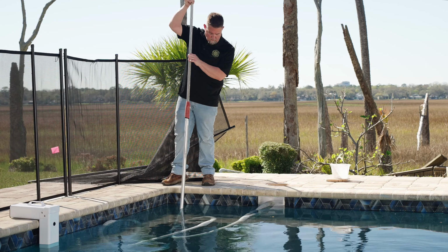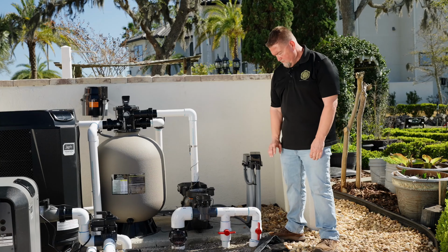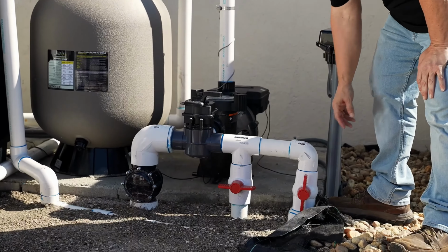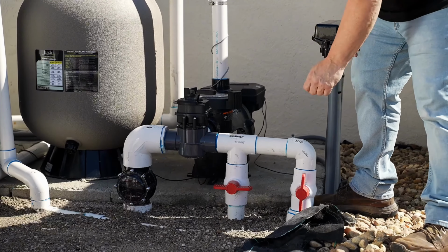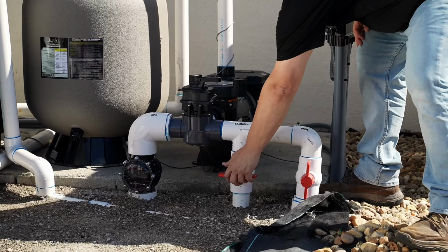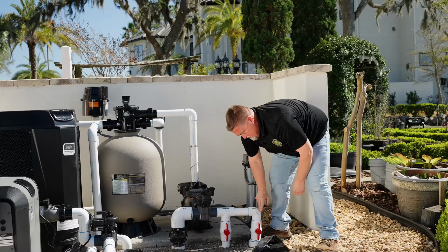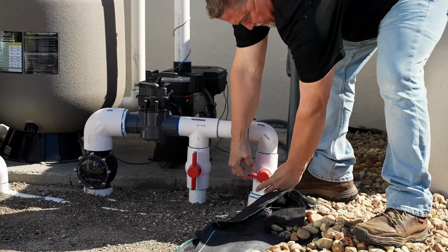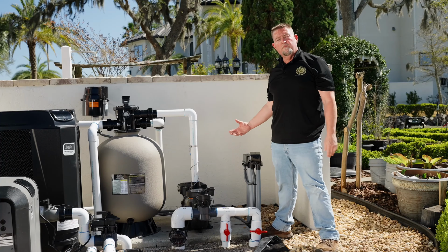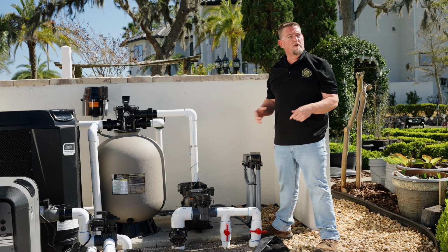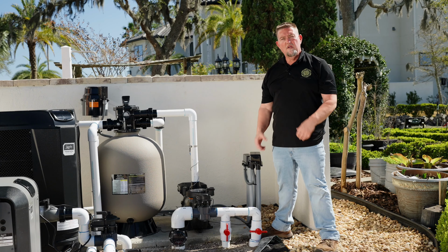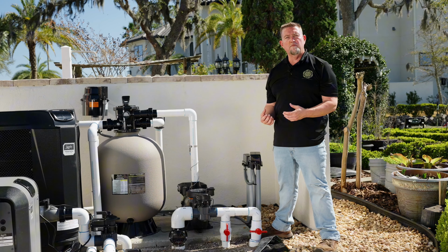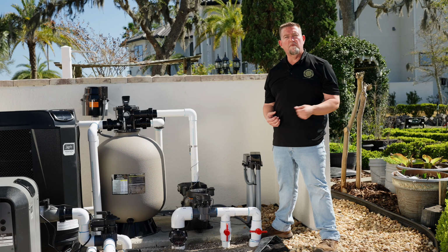When setting up your hose vacuum to create more suction through your skimmer, you want to use the valves on your system to isolate the main drain and the skimmer. So in our case, we want to create more suction from our skimmer, so we will open our skimmer up and shut our main drain down. You can hear the pump right there, just picking up, pulling suction from a different point. That gives me full suction from the skimmer, gives me more suction from our hose and from our vacuum head. That'll help pick up all of the debris off the bottom of the pool.